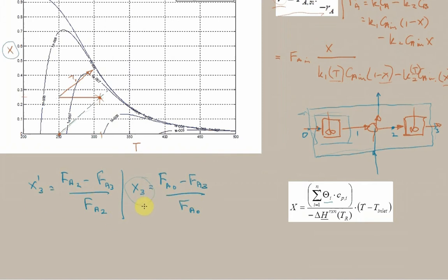So if we are defining conversion in terms of the overall translation from the entry to the exit, then the correct value for theta I will be those values used at the entry point here. In other words, there will be no difference between the theta I that we use for this reactor and the theta I that we would use for that whole system. Right, so that's number one, the first reason why the slope won't change. So that acknowledges that this x is the overall conversion. So that's a special definition for x now, the overall conversion for our reactor system.